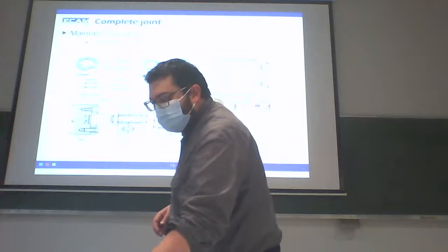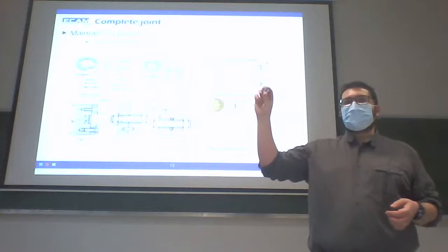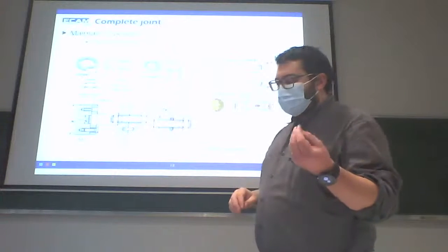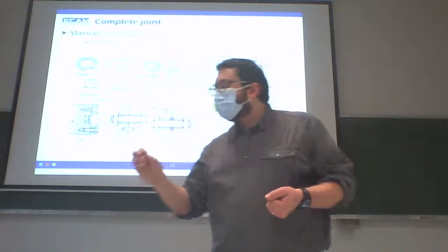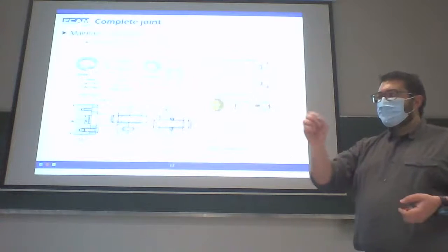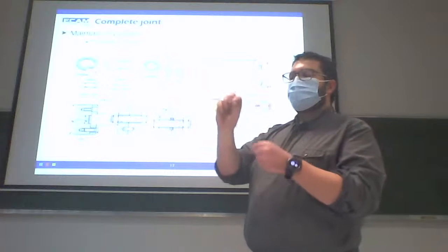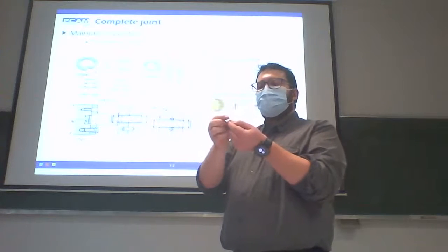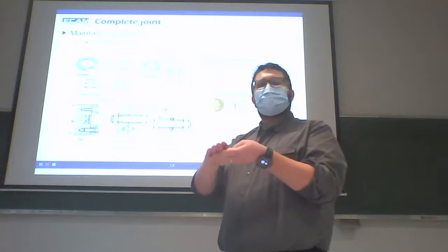So, an example of a standard washer. Here I just increase the surface of contact between the different parts. Second, the lock washer. Here, when I tighten the different parts, I reduce the thickness of the washer, and the sharp edge of the washer will stop the rotation of the nut or the screw.